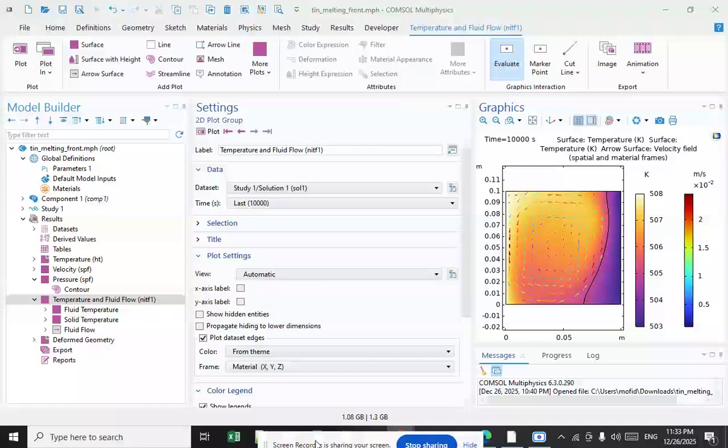The liquid-glass transition is observed in many polymers and other liquids that can be supercooled far below the melting point of the crystalline phase. This is atypical in several respects. It is not a transition between thermodynamic ground states. It is widely believed that the true ground state is always crystalline. Glass is a quenched, disordered state, and its entropy, density, and so on depend on the thermal history. Therefore, the glass transition is primarily a dynamic phenomenon.